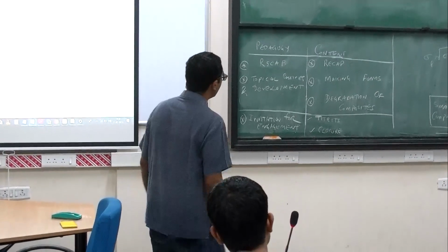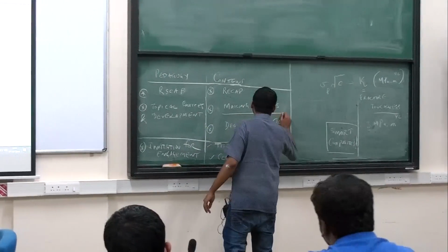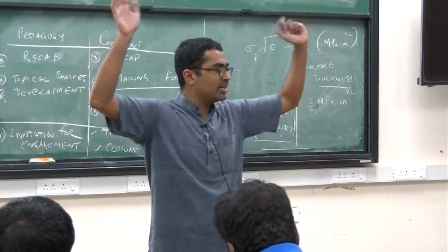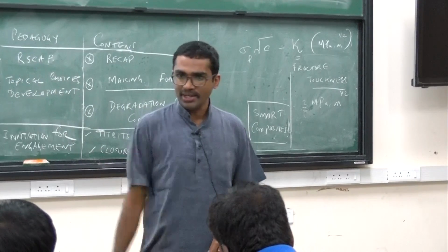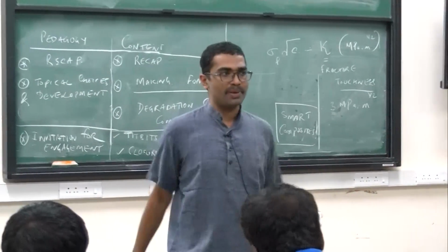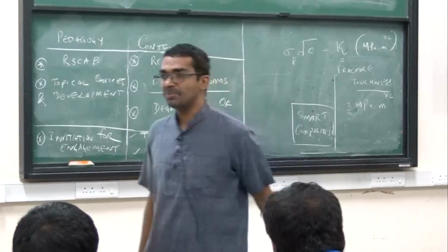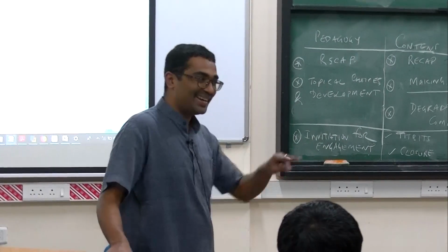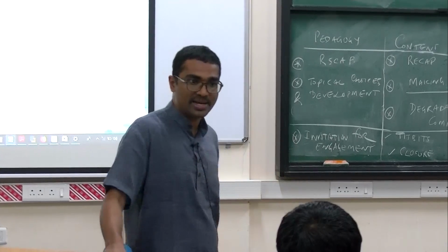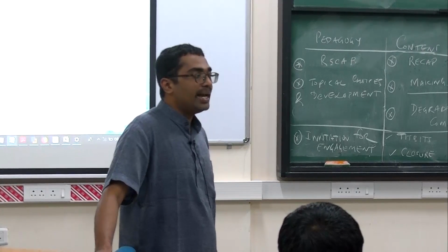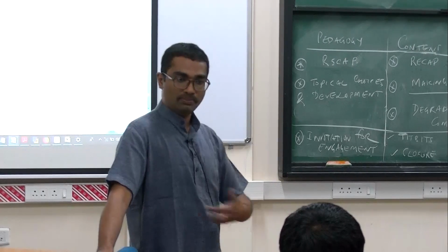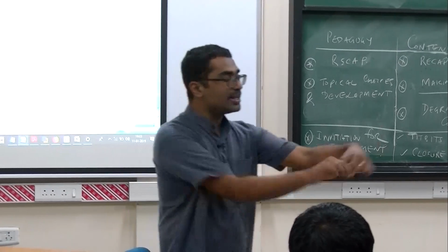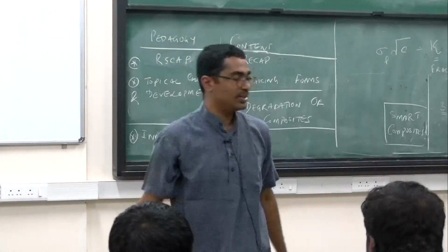Okay. Now, with that as the backdrop, we will think about ways in which we can make foams. So, you all know foams, right? Thermocol, for instance, is an example of foam. You know that, right? So, thermocol, it floats, it's primarily air, predominantly air, as much as 98 to 99% air. In fact, air is one of the phases in thermocol, and then you have an additional phase which is this polystyrene and so on. That particular thermocol is extremely lightweight, and clearly has cellularity, and it has lots of holes in it, and so on and so on.